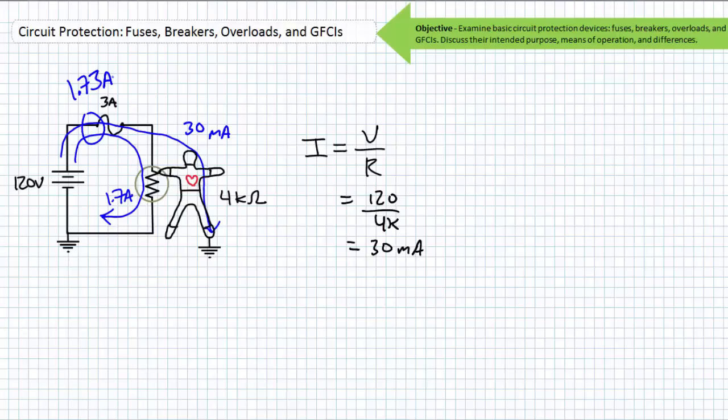As a brief preview of the ground fault current interrupter, consider the outgoing and incoming current during normal and faulted operation. In normal operation, the incoming current to the source is equal to the outgoing current. In faulted operation, the incoming current is less than the outgoing current because the small leakage isn't returning through the intended path.